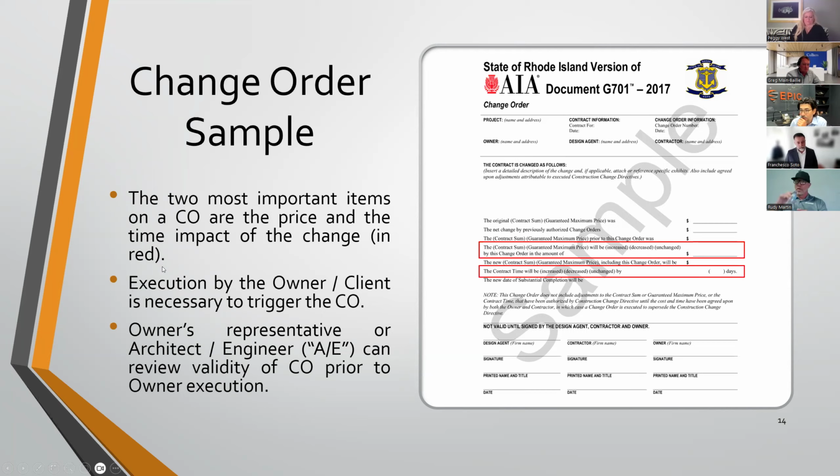And also, as far as importance, is going to be what is considered an executed or an active change order. When it first gets submitted as a proposed change order, the intent to go ahead and do this, there's going to be discussion held regarding that between all parties. Between the contractor to go ahead and substantiate it, the owner rep to understand it a little bit better, the engineer to confirm the validity of it. Is this valid? Or is it represented in the contract or the plans? If so, sorry, can't happen because it's shown on sheet A701, detail 542.